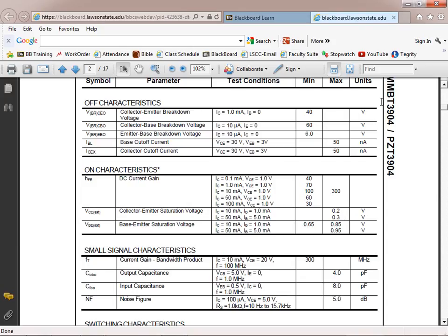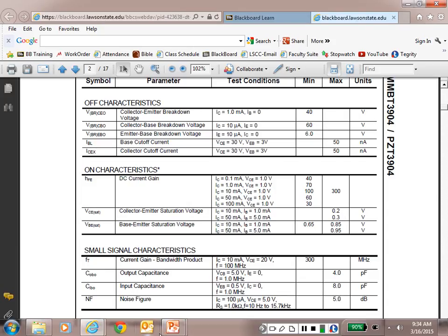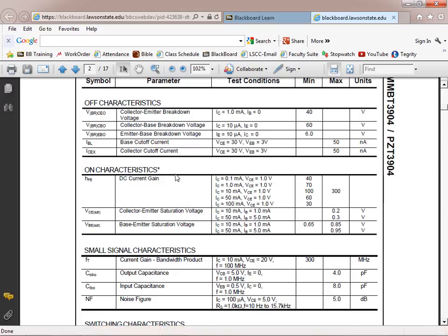Hopefully right in the center. And we'll get in here and we'll look at some of these, but here's your breakover voltages right here. Y'all understand those breakover voltages? It's not an open switch. There's a path through there. If we break over a transistor when it's supposed to be cut off, if we push current between the collector and the emitter, then the transistor is going to be damaged, right?